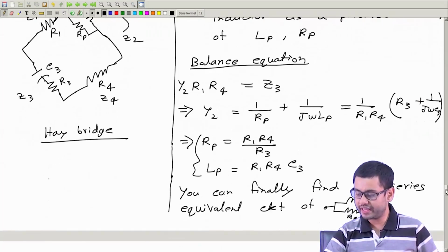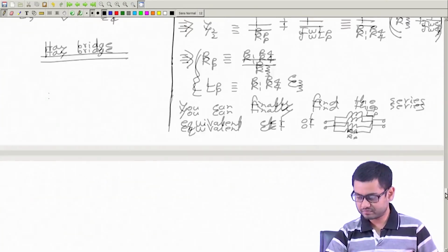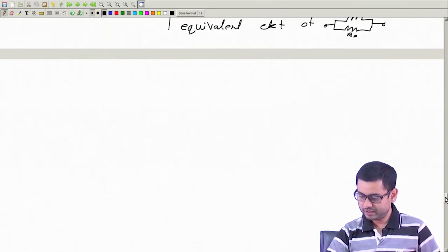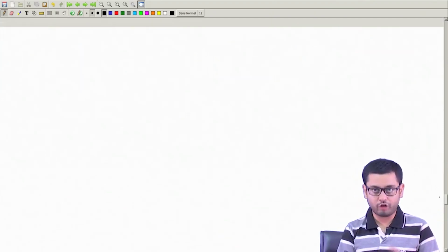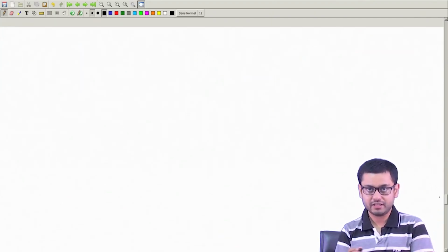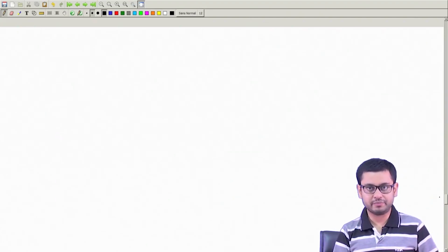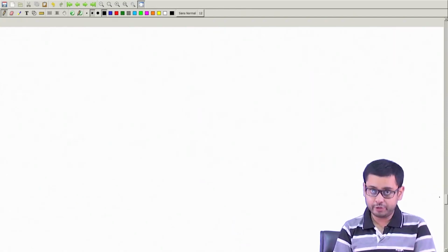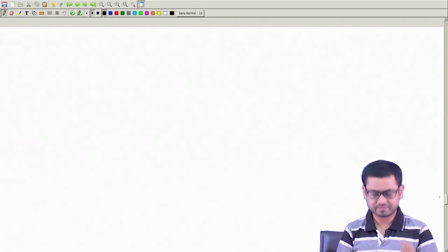We are not doing any new science. So, in that sense this is a bit boring too, but if you do it following this trick of product and ratio bridge, calculation becomes simple. It is even simple during the exam, because you can design the bridge and find its balance equation all in 2-3 lines.